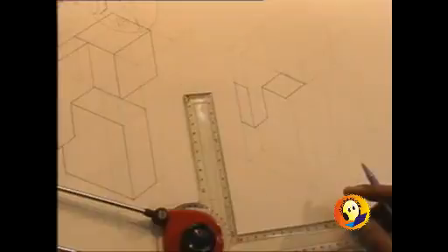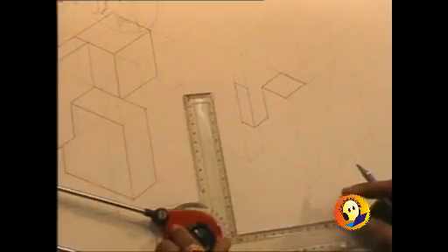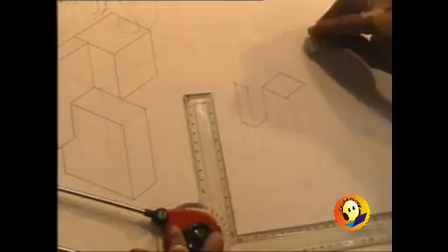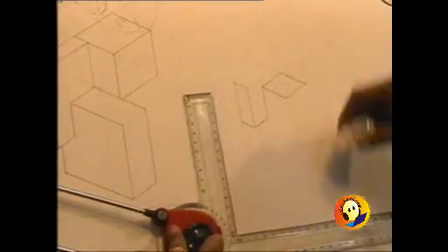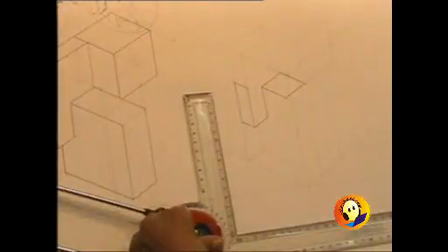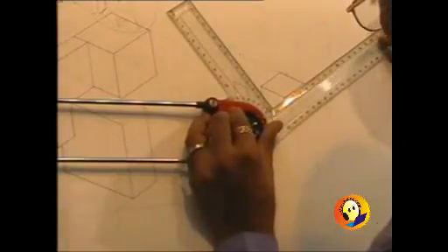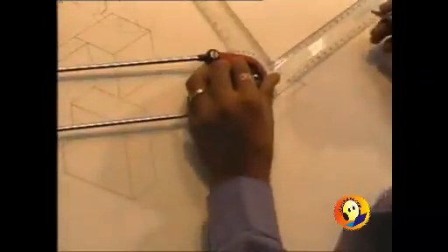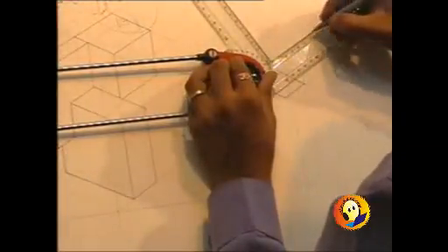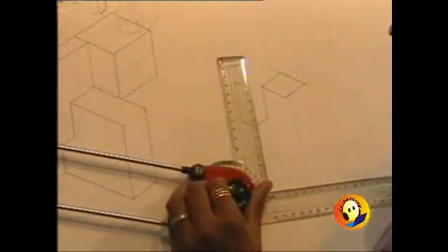And then we said that all the other lines are straight away dependent on the circle. And so let us start with the cylindrical portion which we have, and then after that cylinder we will proceed to the circular part which is there in another block. So now to draw that cylinder, of course the hole in it can be drawn at a later stage, but we should first of all draw the outer circle, outer cylinder, because that is going to help us in drawing the tangent.